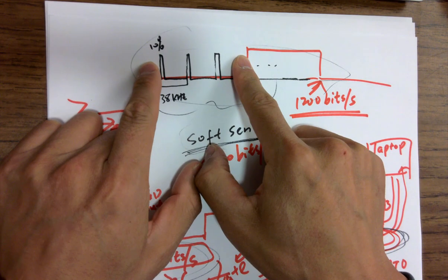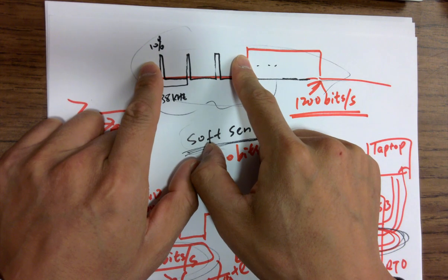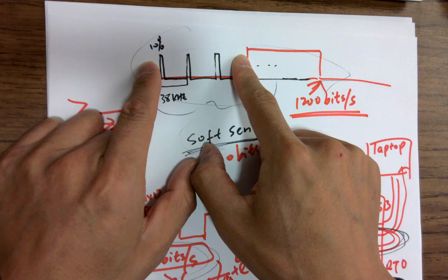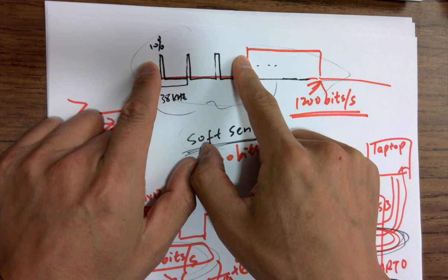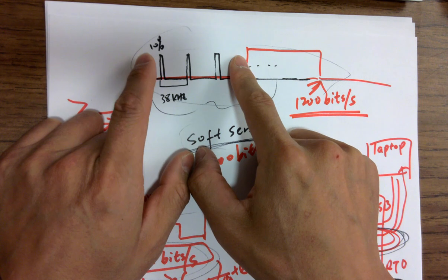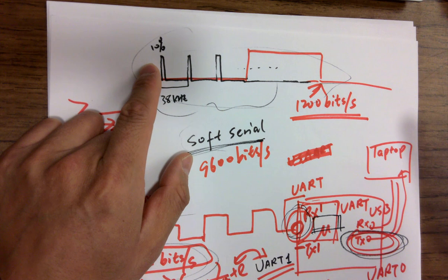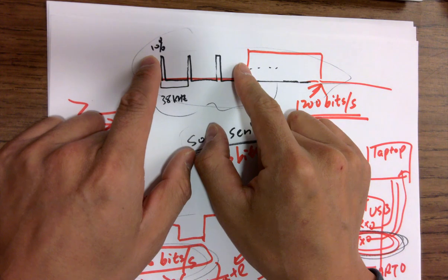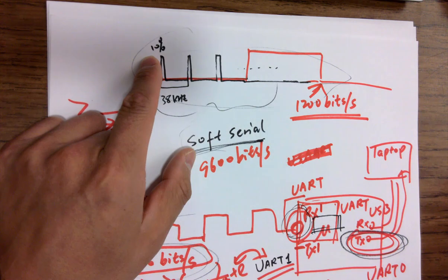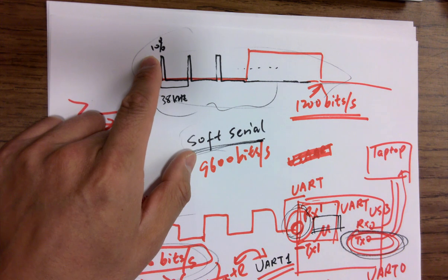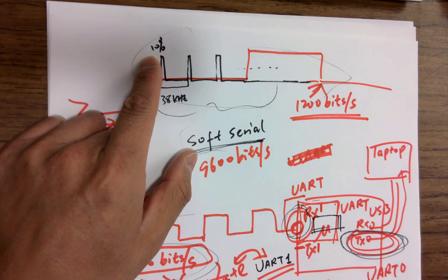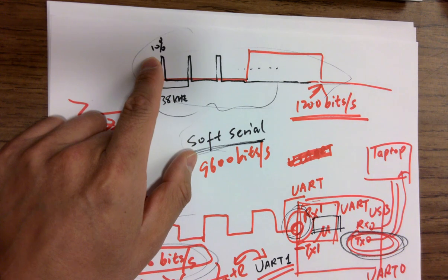You turn it on, then you turn on the timer. It's going to be a different timer, because timer 5 is controlling this PWM, so you have to use another timer. We are using timer 3 for the example in task 1. You can use timer 1, it doesn't really matter. It's very similar to timer 1, because timer 1, timer 3, timer 5 are all 16 bits.